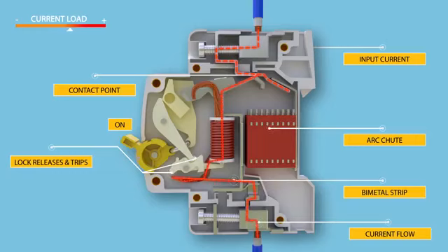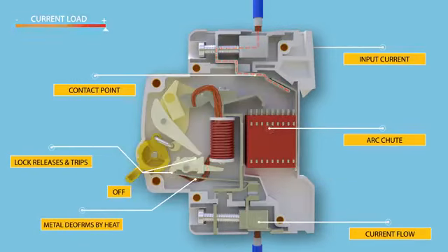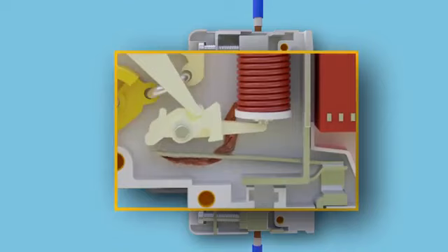In tripping operations, an arc is formed when the contacts start separating. This arc is then forced into arc chute plates, where arc is formed into a series of arcs and at the same time energy extracted and cools it. Closer look how tripping mechanism works.